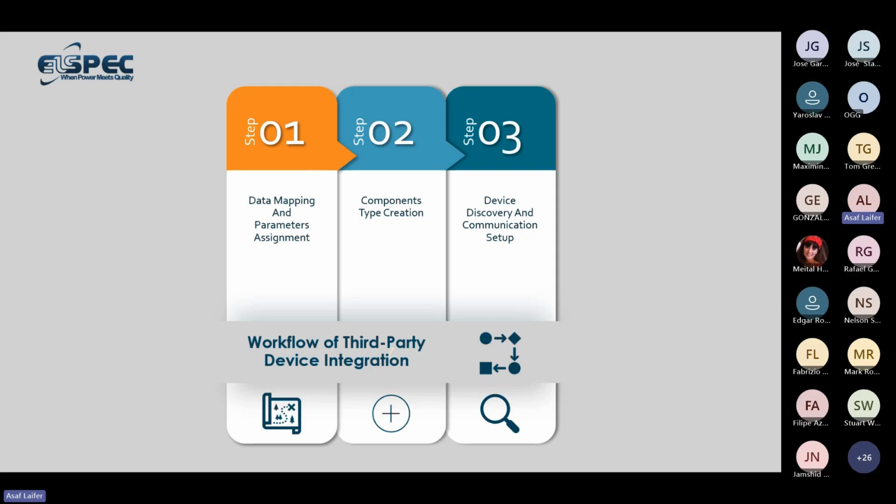Or maybe they don't use register 200. So first we need to take the mapping of the equipment to see what the equipment has in each and every register, and then tell PQSCADA that in register number 200, we have V1 RMS, and register number 202, we have V2 RMS, and so forth. So this is the mapping. This is the first step of each and every integration.